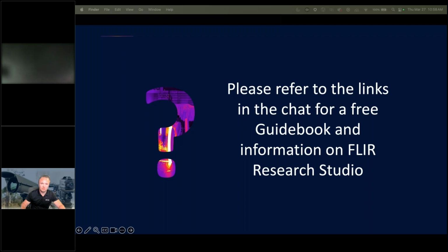A question came in regarding camera calibration. There are 2 types of camera calibration: factory cals and user cals. The factory cals are going to come with a 1-year sticker, and we have to do this according to NIST rules. The camera will generally be accurate longer than that, but we can guarantee that 1 year.